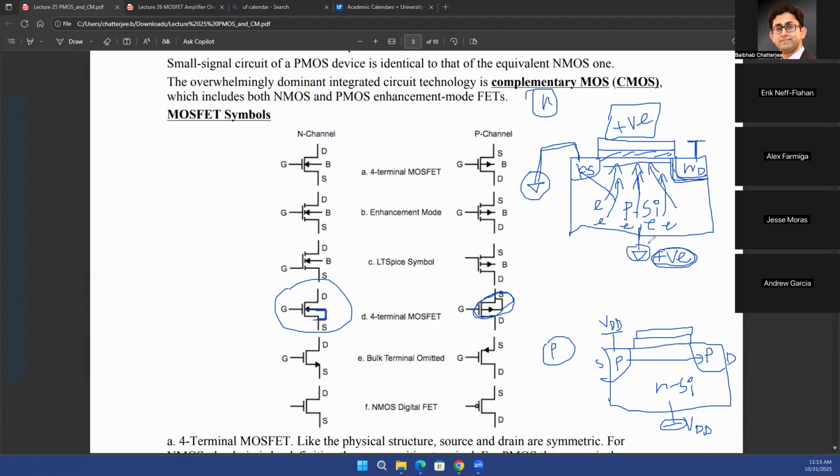So if you're applying a very small voltage, let's say 0.1 volt, 100 millivolt here, that does not reach the threshold voltage. So your PN junctions do not fully turn on. Of course, there will be more leakage current, but they do not fully turn on to create havoc or create basically thermal runaway issues in the MOSFET. But again, you can play around with your threshold voltage.